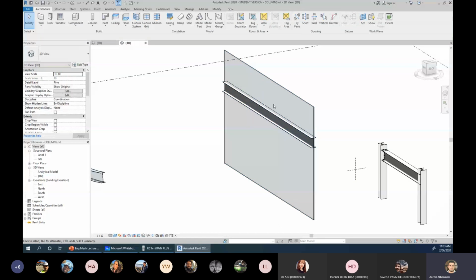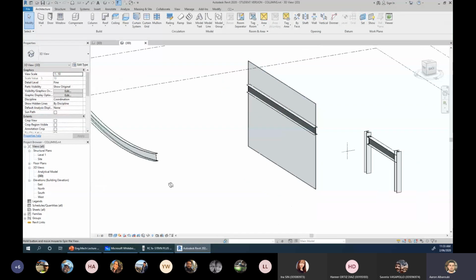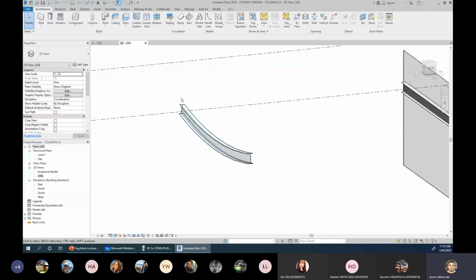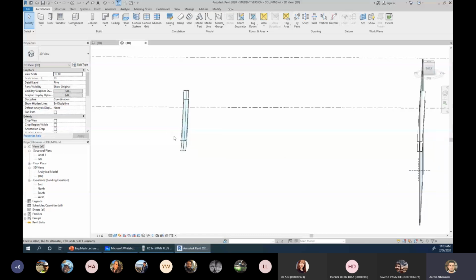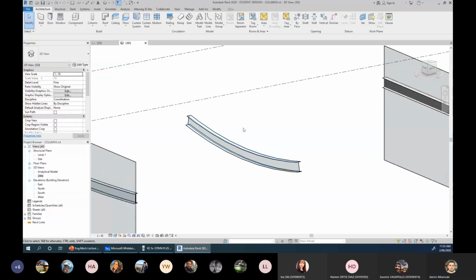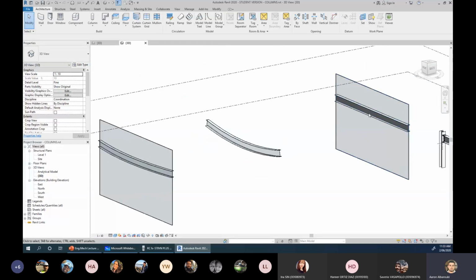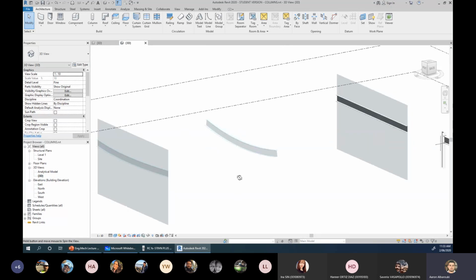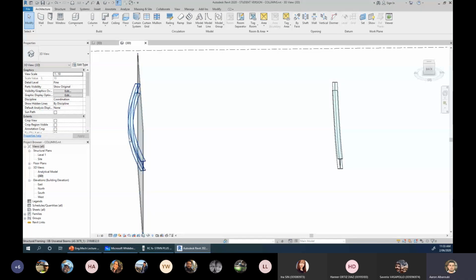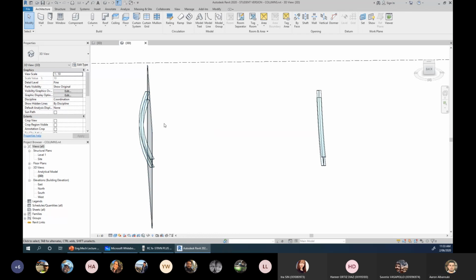So if I'm pushing from the top on the beam, the beam will deflect that way. Look at it. It stays within its plane, but is just deflected downward. Deflected down, that's bending. But for any reason, if I push at the top, and this may happen a lot, and for some reason the beam buckles to the side, look at it here, outside the plane, we call it buckling. So do we understand the difference between bending and buckling? All good, guys? Anyone not clear on that?